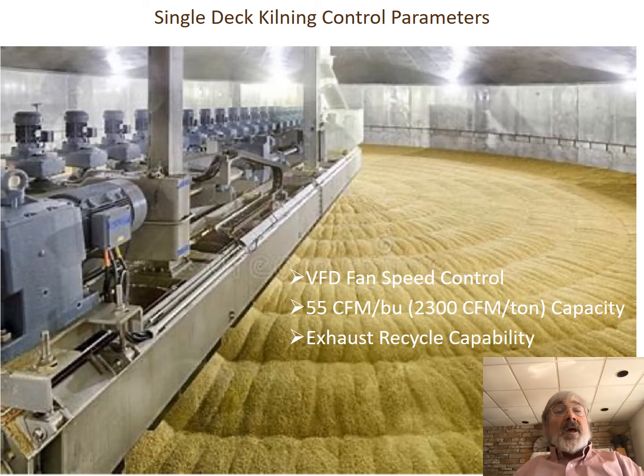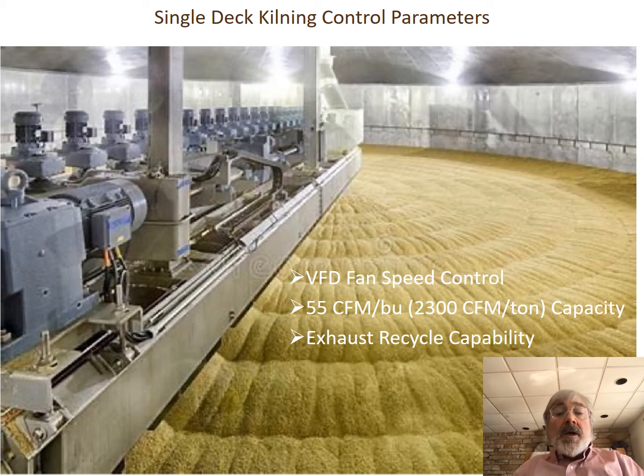So bringing, as we'll see later, high energy, high humidity air back into the burner will raise the effective temperature of your bed. Using recycle will raise the effective temperature that the grain sees in your bed.